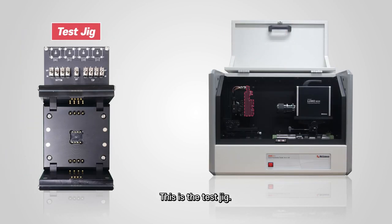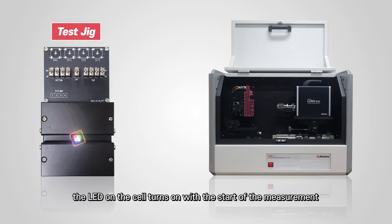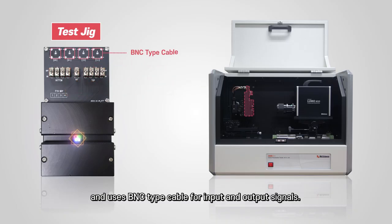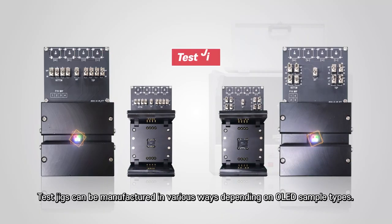This is the test jig. Once the cover of the jig is closed, the LED on the cell turns on with the start of the measurement, and a photodiode is utilized to measure and record this LED's luminance data. It is used for both top and bottom emission type samples with 4 luminance regions, and uses a BNC type cable for input and output signals. Test jigs can be manufactured in various ways depending on OLED sample types.